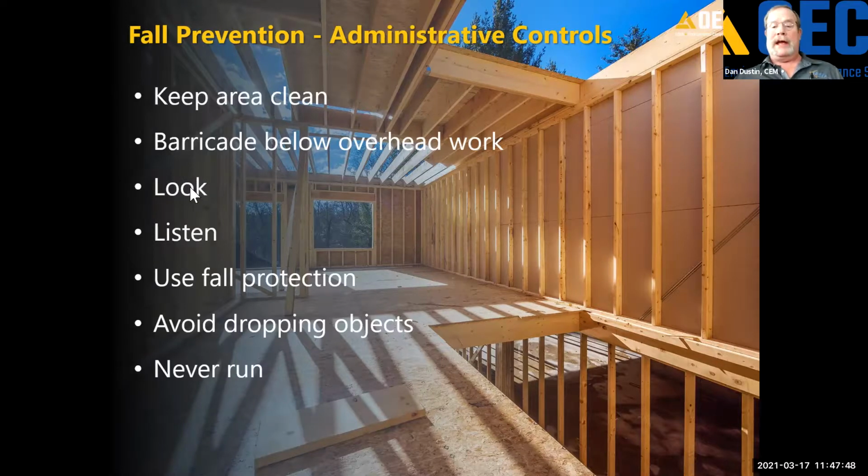Look and listen, pay attention to what's going on. I've got to believe that some of you have walked out of a building under construction only to see someone swinging a load over your head with the hoist or the overhead crane, the tower crane. You know, look and listen, pay attention. Use fall protection anytime it's needed. And if you look at the example in the picture, I have a wide open stairwell with no stairs. There's no fall protection here at all. This should have been addressed as soon as that opening was created.